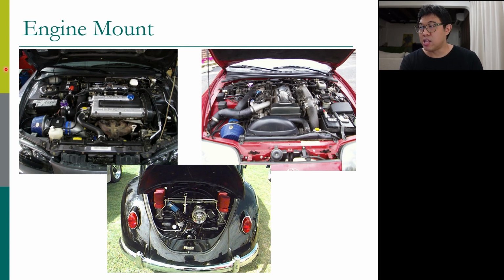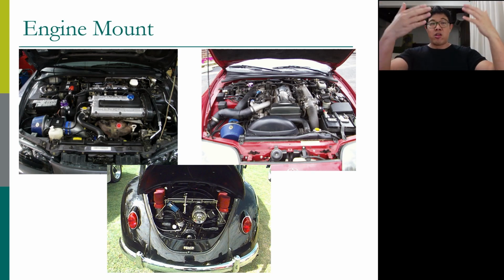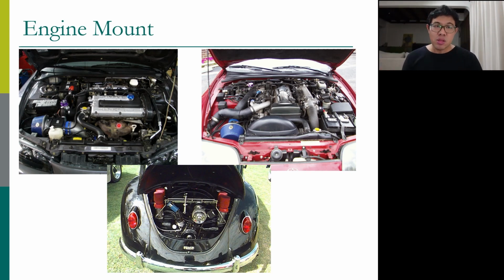The engine needs air to cool, to remove heat from the engine through the cooling system. That's why we put the engine in the front, so that there is a lot of air pushing inside the engine compartment. If you put the engine in the rear, you may have problems with the cooling system. You cannot find enough air to cool the engine.